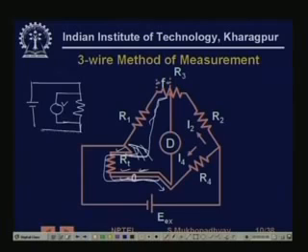These wires are also long, but they are the current carrying wires. These other wires are also long, but they don't carry current because this is a voltmeter, a high impedance device. Therefore you sense the potential across the resistive element only and not on the leads. So if you have a 4-wire RTD, you can use this circuit. This is the 4-wire method.